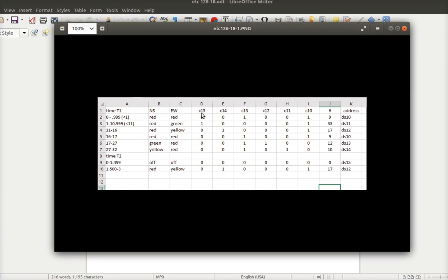But Allen Bradley does have that mask, and it's something you really got to work with some, and I'm just trying to introduce you to it and get you to where when you see a mask, you sort of know what's happening there. Usually your masks are set at all Fs, which in hexadecimal is a 1 in every bit position.